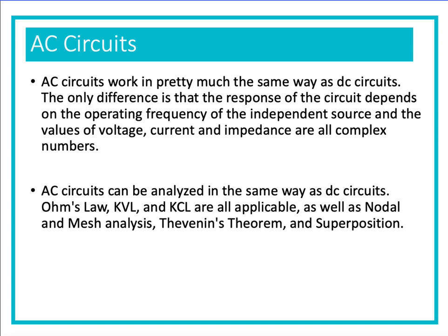Anything that we've learned so far that can be used in circuit analysis, Ohm's law, KVL, KCL, nodal and mesh analysis, Thevenin's theorem, superposition, all of those work the same exact way with AC circuits. The process in this class of nodal and mesh analysis we don't tend to do because we don't want to make you do matrix equations with complex numbers, but you could if you wanted to. You could do all the same processes that you've learned so far.